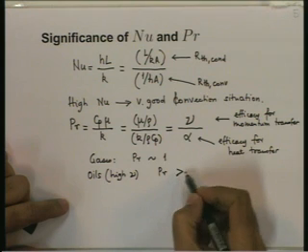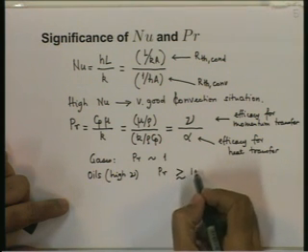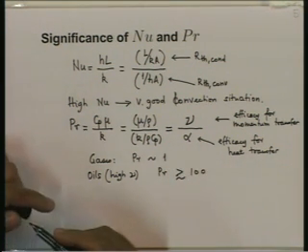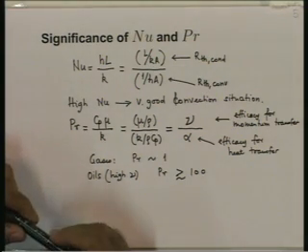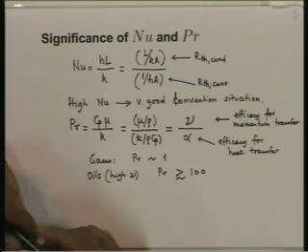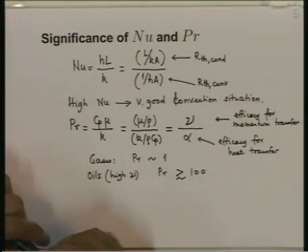You take oils, say lubricating oil, engine oil of a car. Here we have high viscosity. The Prandtl number is of the order of or greater than 100. Prandtl numbers of 300, 500 are not uncommon, particularly for low temperature oil.